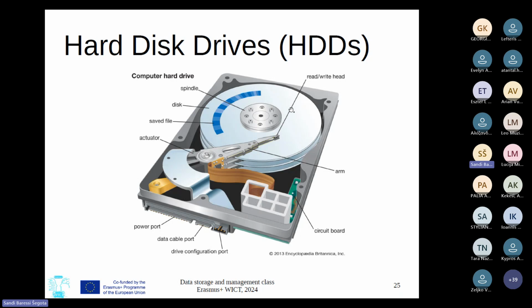And you have a limit to this, and this limit defines how many bits you can store on the disk. So you can calculate it: if you have a 0.01 degree rotation, you can calculate how many individual data points you can have on the disk. So to increase that, people started stacking multiple of these disks, one on top of each other, into a single enclosure.